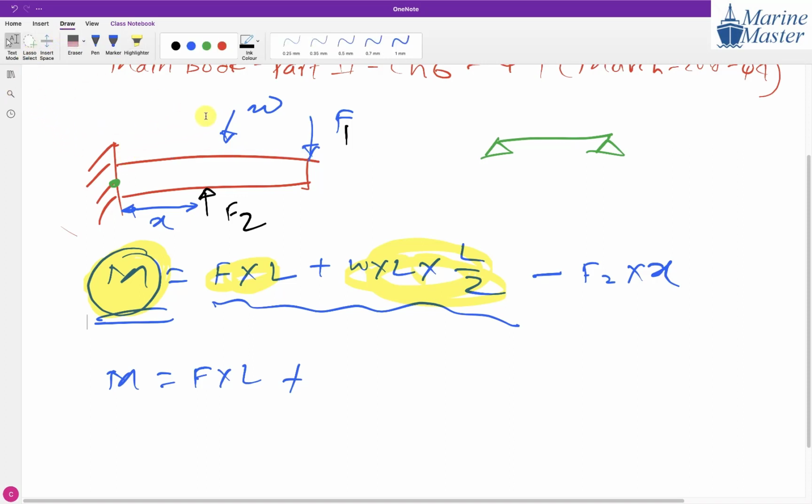One last thing. So you mean that if it's a cantilever with more than two forces, like two forces downward and one or two forces going upward, as we have shown here, in that scenario we can apply this clockwise, anticlockwise formula? Yes, in case of a cantilever. While calculating bending moment, we will not see hogging or sagging. We will see clockwise, anticlockwise, guys.